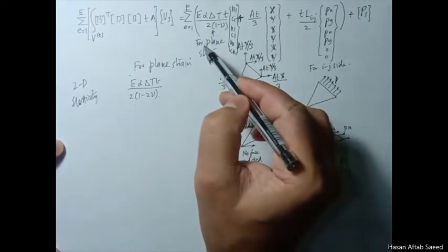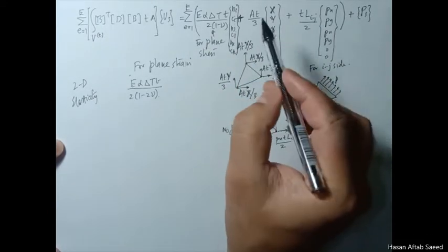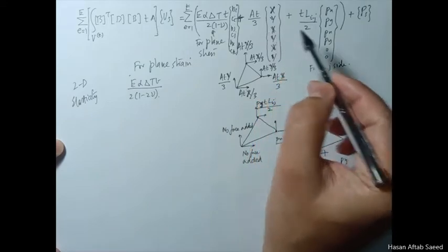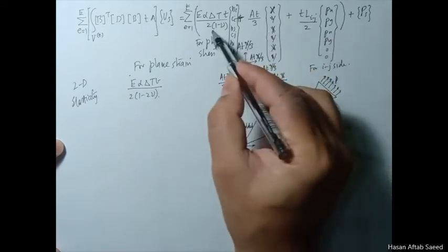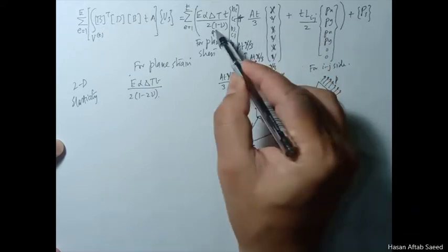On the right hand side we have four components. The first three, namely the force vector because of temperature, body force vector, and the pressure force vector, have to be done on the elemental level.